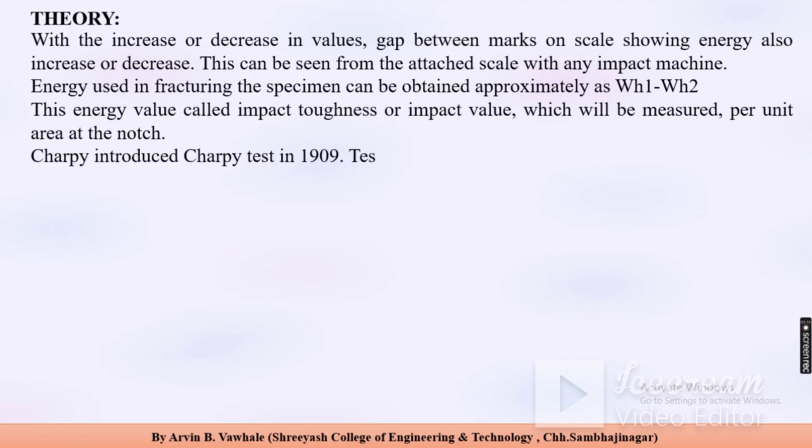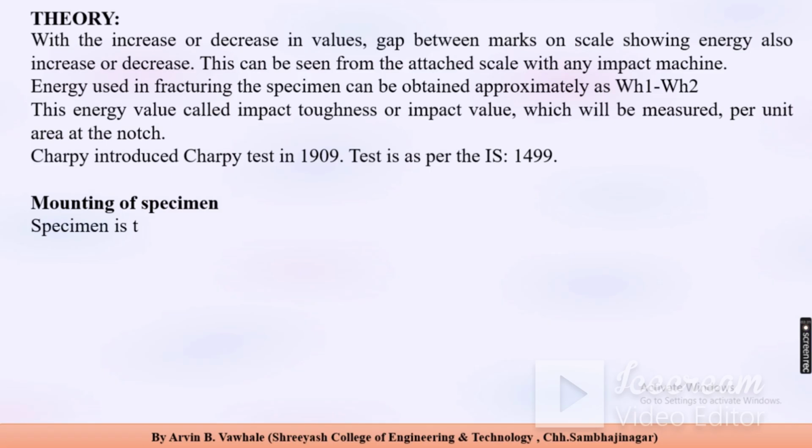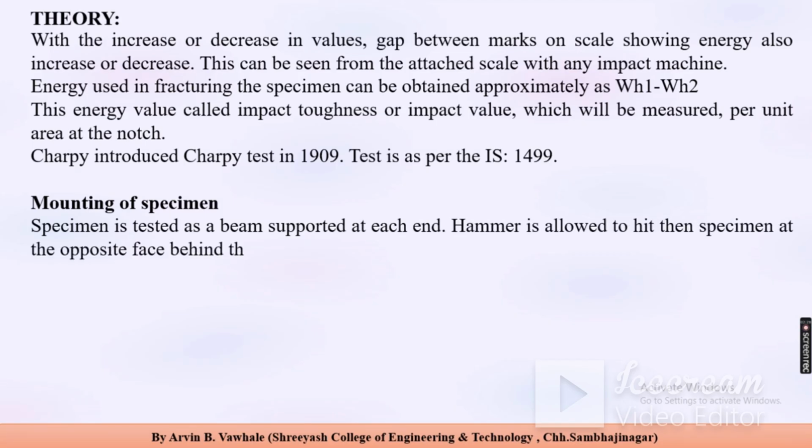Charpy introduced the Charpy test in 1909. The test is as per IS 1499. For mounting, the specimen is tested as a beam supported at each end. The hammer is allowed to hit the specimen at the opposite face behind the notch.